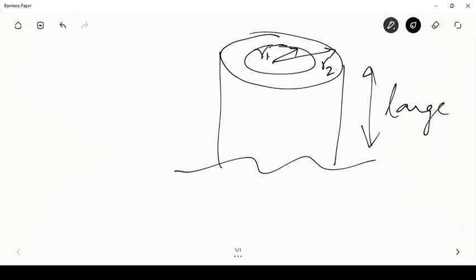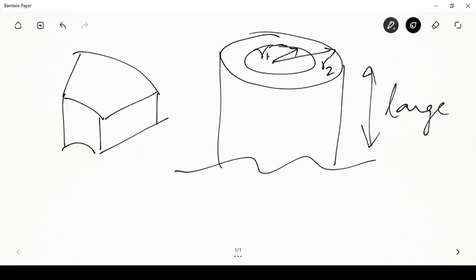Now, if we try to look at the energy conservation in a cylindrical shell like this, let's take a small portion of the shell here. Now, let's for the moment ignore the variation in the theta direction, that is in this direction. We'll only consider the heat conduction equation in the radial direction, and we'll write the equation for the radial and the z direction to make it indicative. Finally, we'll be solving only a one-dimensional case for the radial direction.